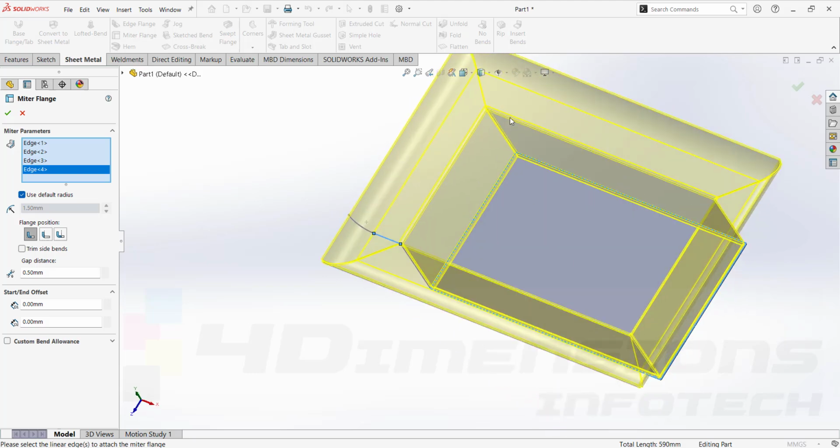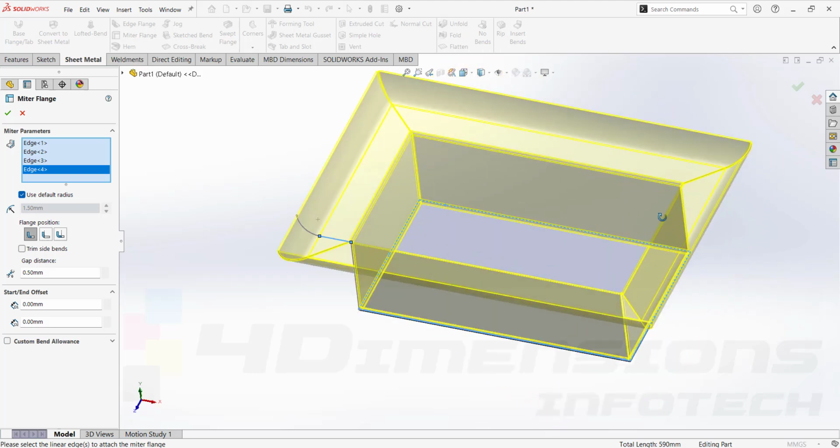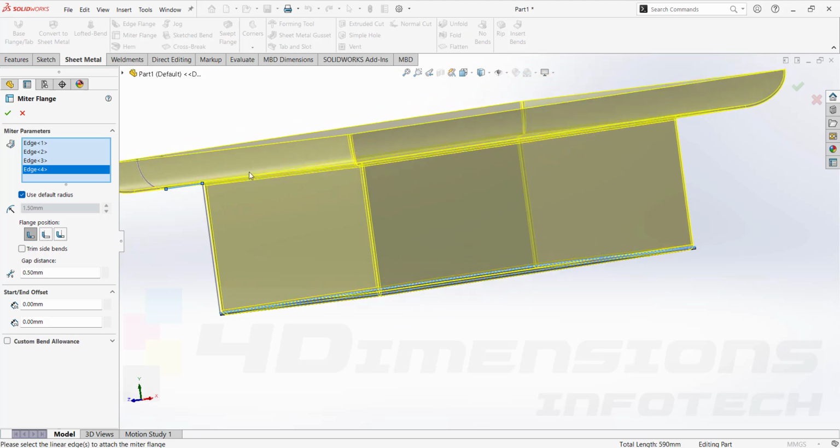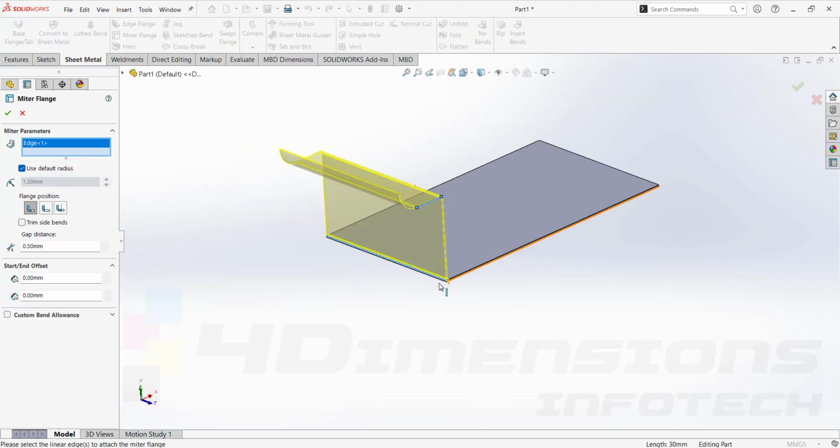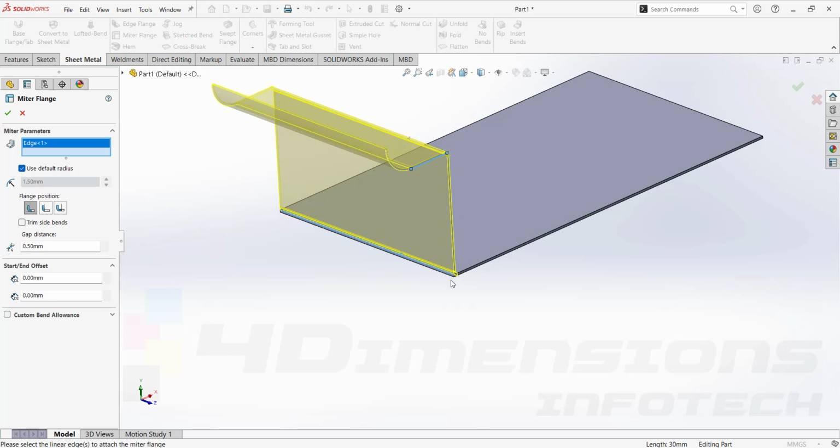You can see the corner treatment here. It is completely packed, having only one gap at each corner, that is of 0.5 mm, which we have given here at the left side in model tree. Suppose I clear the selection and only select one edge, and I want to drag this miter joint inside from the corner at a particular distance.